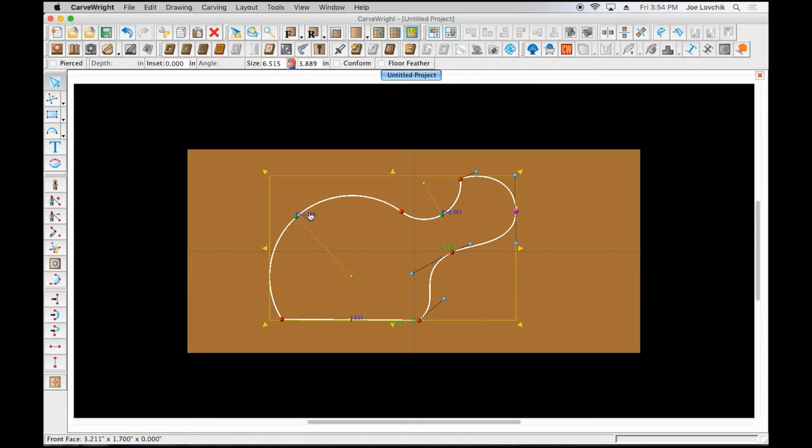We also have what we call the constraint numbers. Anytime you click on one of these numbers, and you just want to get out of it, press the escape key and it'll escape you out of that number. What these are for is input fields that allow you to type in dimensional information so that you can be very precise in the layout of your drawings. So I can put the number 2 in here and set that arc at a 2-inch radius,